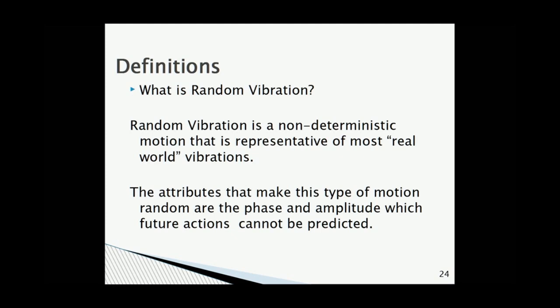Now, going back, I told you that you would appreciate the unit G RMS, because RMS expresses magnitude for a varying quantity. And now you see why it's used in random vibration testing, because random vibration testing has content which varies randomly. So GRMS is the unit of measurement you would want to use to express the magnitude of a varying quantity. So now you understand why GRMS is used for random vibration testing.